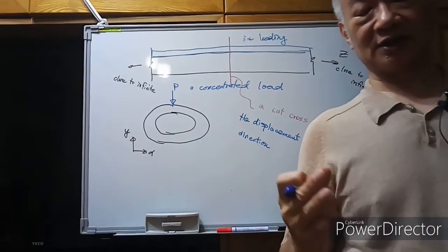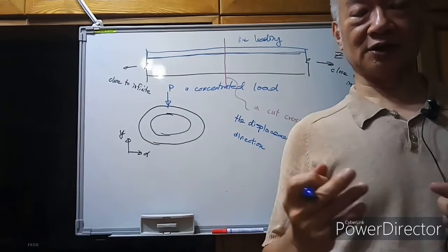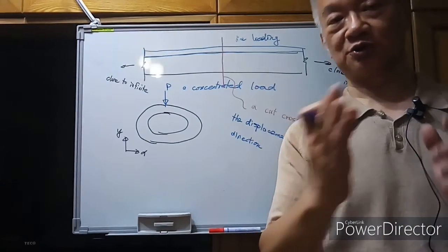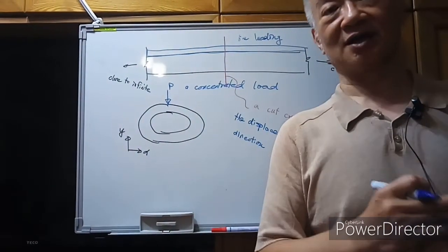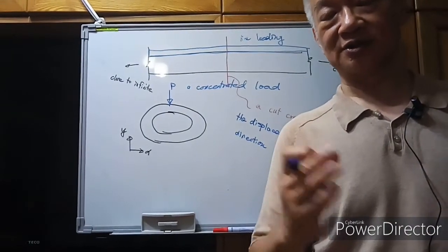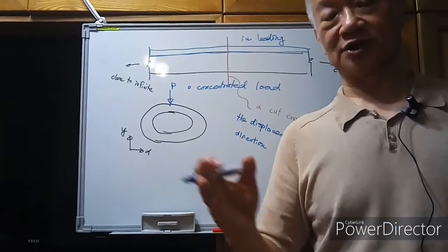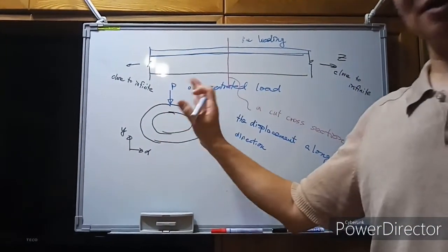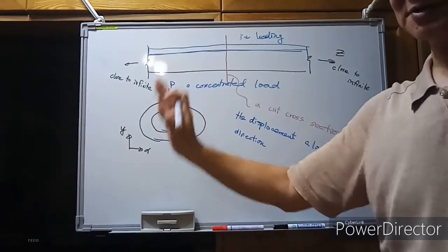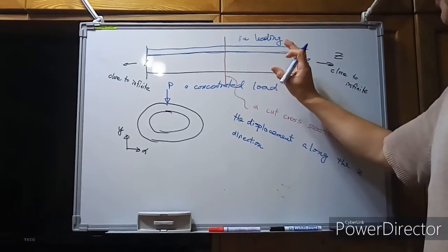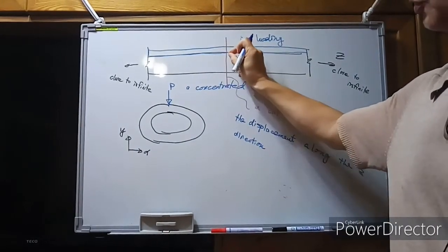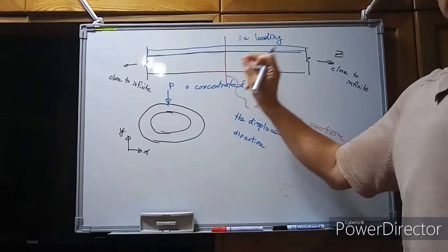If you understand all the assumptions about the plane strain problems, the cross sections are always the same no matter where we cut: the geometry, the applied loadings, the boundary conditions, and also the material properties will not change. So no matter where you cut, everything is the same. Then for any cut cross section, where will the points move along the z direction?